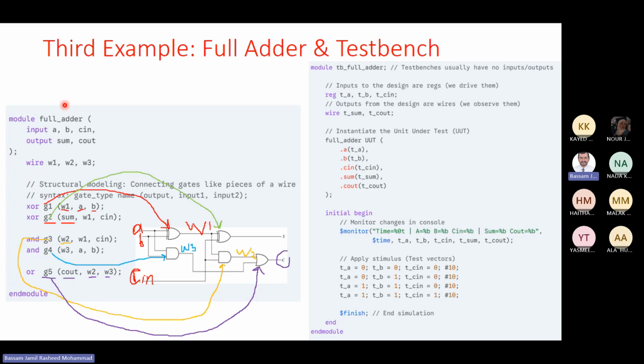Okay, so here is my adder. I instantiated the adder. Full adder, that's the module name. Then what is a UUT? It's an instantiation name. I can call it U1, I can call it X, I can call it B, I can call it Sammy. I can give it any name. In fact, if I ignore it, the tools sometimes will create their own.